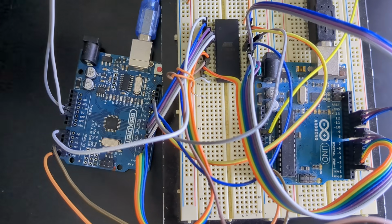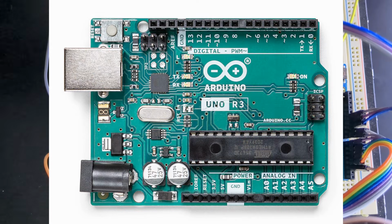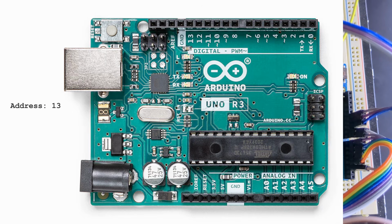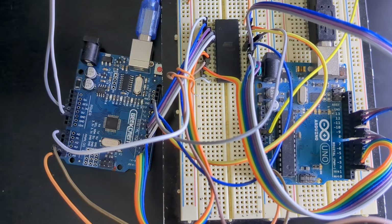To program the ROM, I'm going to use an Arduino. Now this is a bit of a rat's nest, but it should do the job. Now the Arduino by itself doesn't have enough I/O to program the ROM chips that I'm using. I've got 13 address lines, 8 I/O lines, and a few control signals, so I don't quite have enough for that. What I'm doing instead is using 2 Arduinos, so one as a master and one as a slave.